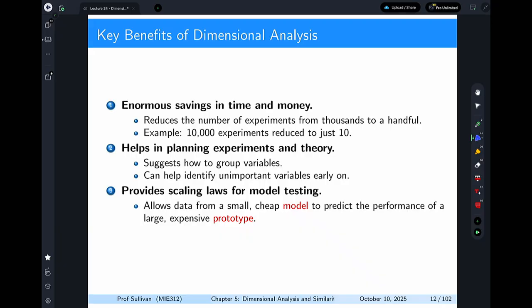So if you have a Reynolds number, and because it's a function of 4 different variables, you just so happen to have different combinations of those 4 variables that yield the same Reynolds value? That's correct. We're treating those 2 scenarios as the same? Yeah. One of the examples I'll do in the next chapter is looking at Reynolds' pipe experiment. A Reynolds number of about 2,000 to 3,000 is associated with the transition from laminar flow to turbulent. It doesn't matter what the fluid is in there. It's always going to be the same thing.